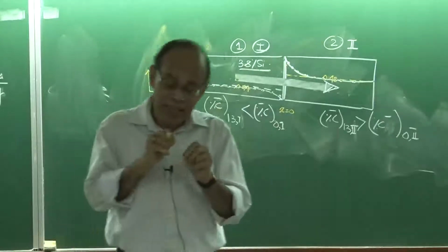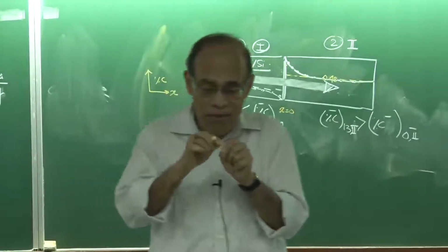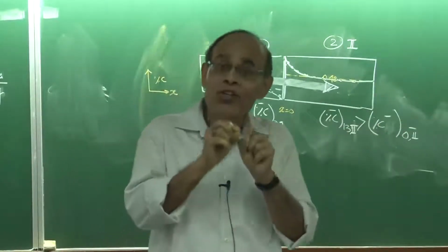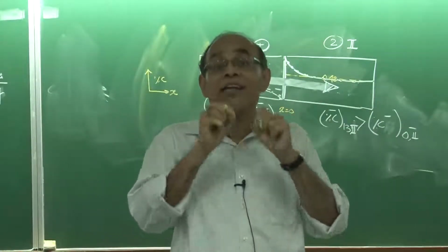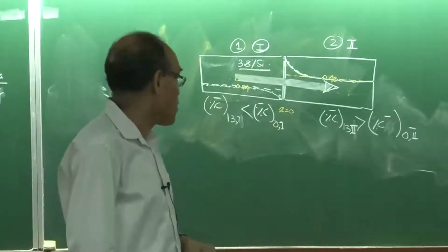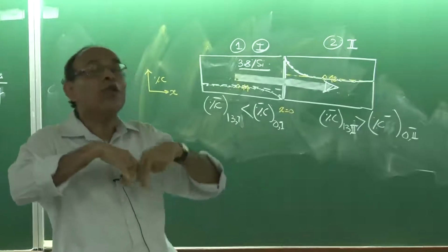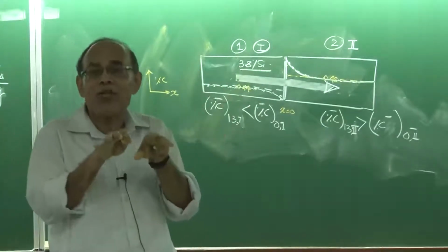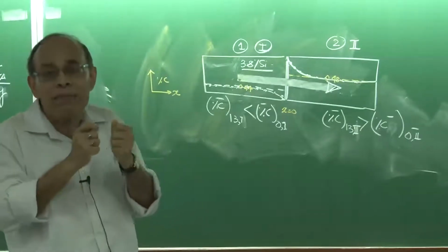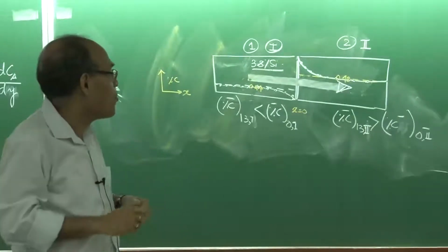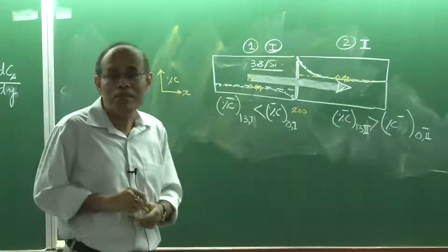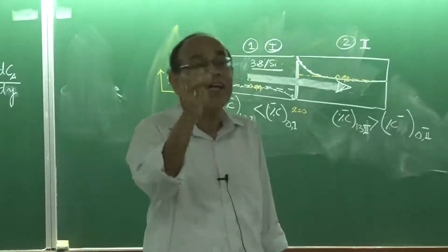carbon now finds that it is friendly with iron anyway, that is the scenario on the other side also, but it now contains a better friend like niobium or tungsten, which has an even greater affinity towards carbon. So the carbon is not willing to leave the system, and its activity is therefore not visible at all. It is in a very quiet condition, as if tied up very friendly with a niobium or tungsten atom, so the activity can go down. Now, in multi-component systems, the presence of an additional solute